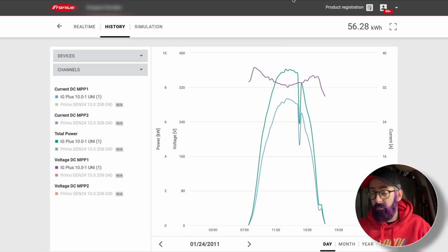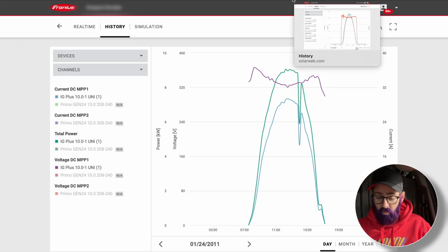So if we're comparing production, we're still at 97% of the production on this array, either because the panels are just holding up or because the inverter is able to better use them now. If you look at the manufacturer specs, I think that they say like 5% degradation in the first 10 years, and for the rest after that, we're looking at like 15-20%. Panel manufacturers will over-exaggerate that sometimes, but all I'm saying is we're doing good.